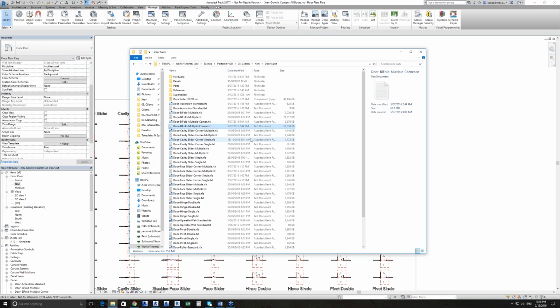Now, because of that, it does mean when you try and load it into Revit, it takes Revit a bit of time to display the type catalog because it's trying to load that many types. Because we wanted to make all the types available to the end user, we've decided to distribute it that way, but you can very easily delete the types that aren't applicable to you.